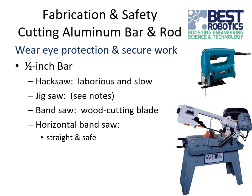For cutting the aluminum, this is specifically talking about the aluminum bar and aluminum rod, the thicker pieces of aluminum. There are several different ways you can do it. A hacksaw is actually a really good way to do it. Sure, it's a little bit slow, and you've got to put in some muscle power, but it's safe, it's pretty well controlled, and you don't need a lot of special equipment for it.